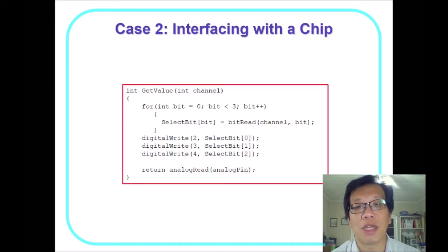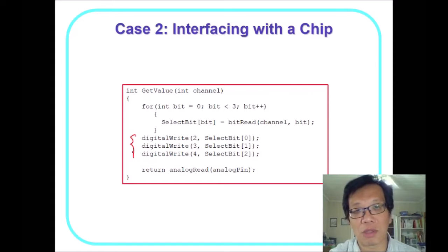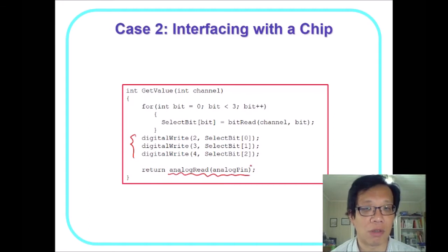If we specify the digital pins with the corresponding number like 000, 001, 010, those 8 combinations, we can actually select which channel gets into analog 0. When we are reading the analog inputs, we just do the regular thing, because we just take analog 0 into consideration. But by controlling the 3 digital output pins, we can expand our analog input from 1 to 8. This can be very handy.